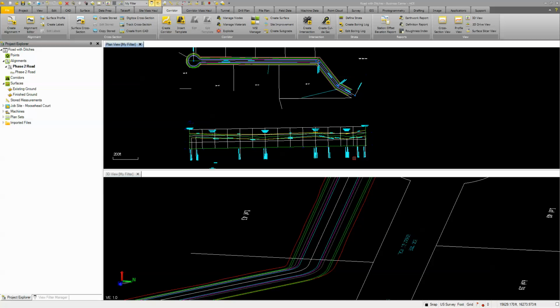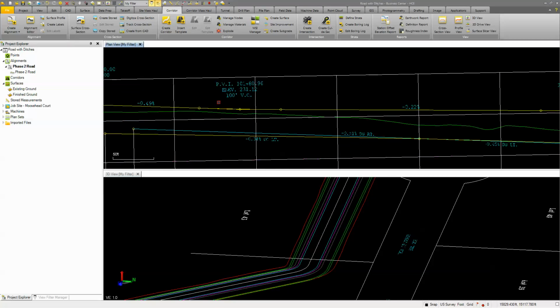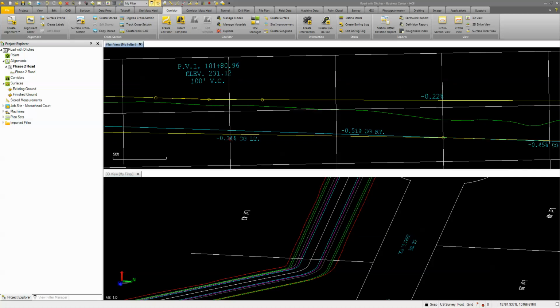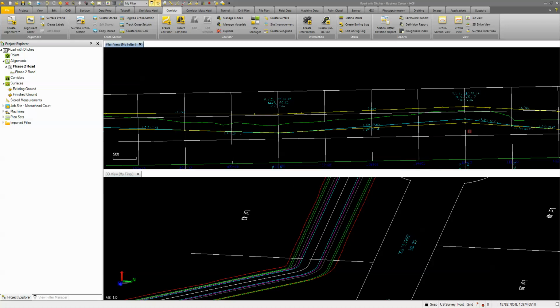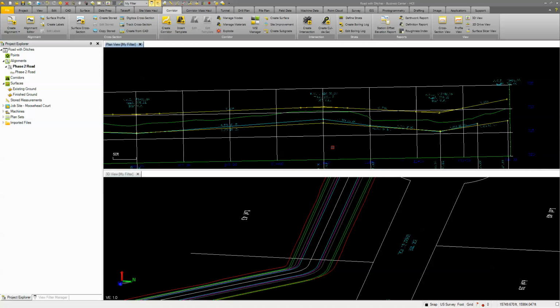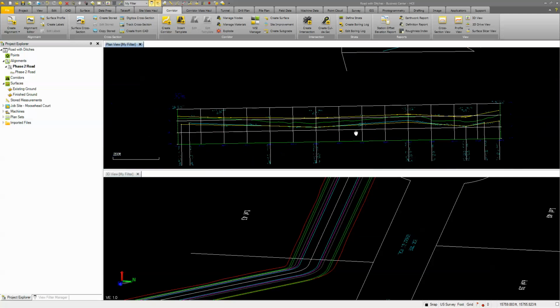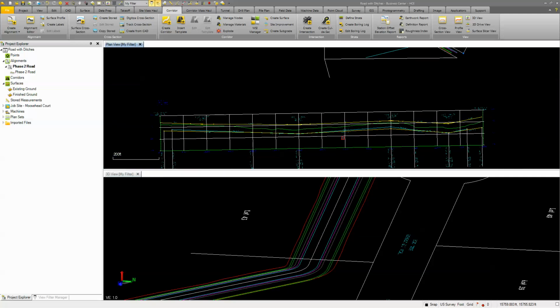my top plan view. So what I have is I brought in a CAD file, and that CAD file gives me my CAD line work, and it also brought in the profile that's going to show me the vertical information for not only my center line of my road, but also my left and right ditches. So you can see here I've got a ditch grade on the left and a ditch grade on the right that follow the road or go down the length of the road linearly, but they have different elevations. So I need to tie the ditches into those road or ditch profiles.